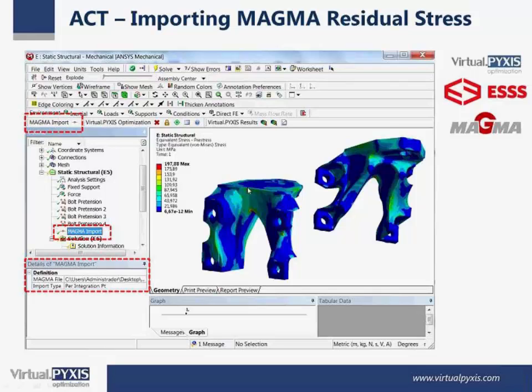So you can use this information very soon. And also the Young's modulus, sometimes it varies from part to part of your model, and the yield stress, I told you, can influence, for example, if you're using plasticity analysis, you can use a new Young's modulus, a new yield stress and tensile strength to prevent or to use the right plasticity information of your material.